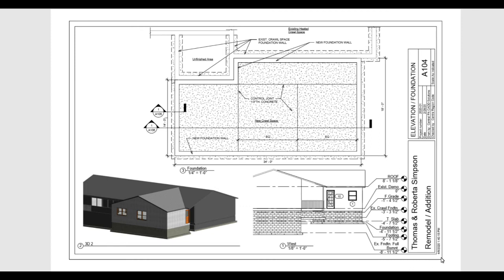set of drawings on the title block, in this location we're going to have project name and description. Right here, this is going to be your timestamp. So this is basically the time and date that this set of drawings was printed. So a lot of times this is going to be different than the actual project date. Project date is typically going to be the same the whole way throughout the entire set. This is going to vary obviously because things will be printed at different time frames.